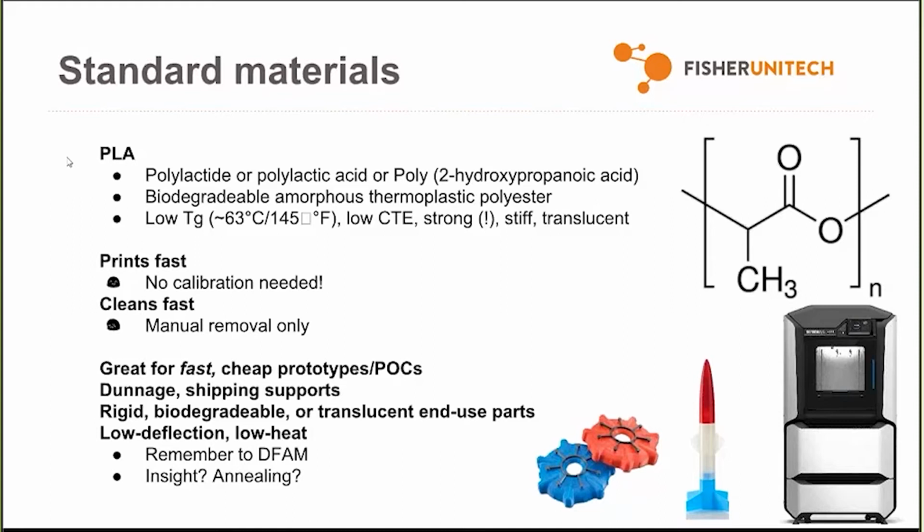Use it for clearance verification. Maybe build a complex assembly, but just the outside shell with a sparse infill. Shove that into the position, make sure it doesn't bump into anything. So that kind of stuff. It really works great for anything that doesn't need to be solid, because that's the default build style in GrabCAD.